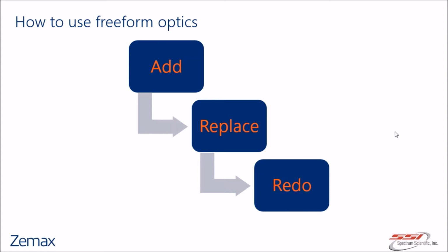After the initial NRE costs for the freeform mirror, which is better than lambda over 10, the cost of the unit is under $200. And in higher volumes forecasted for the end of 2018, their price drops to below $100. And in high volumes, say commercial products, this price can go down even further. Freeforms for volume production have similar costs to precision mirrors in production runs.